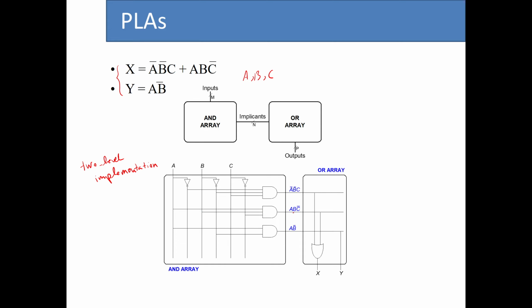And finally, for the implicant required for creating y, I need a 2-input AND gate, with inputs connected to a and b bar. If some implicants were shared between the two functions, we would only need to create one instance and reuse it.